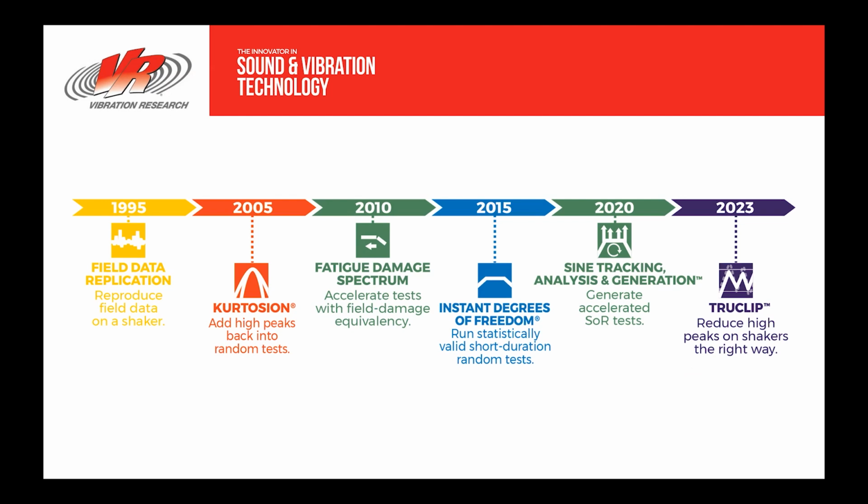STAG, or sine-on-random test generation, is specifically for developing vibration tests for products that live in environments with dominant sinusoidal content, such as engines. STAG ensures that all forcing functions are realistically replicated for the correct duration during your vibration testing.